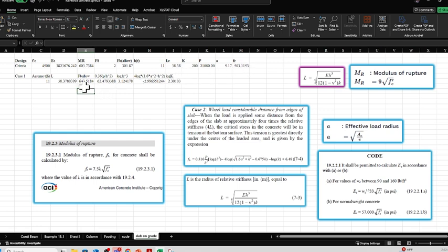Next, if I use the axle load and increase this to 42,000 pounds, and hit enter, and then make this A 10.3 for 2 tires, that will give me 1200, way too much, so it didn't make it. I think this is made for like 1 tire. So let's go back to 21,000 and make this 5.17 again, and that comes out to 643.